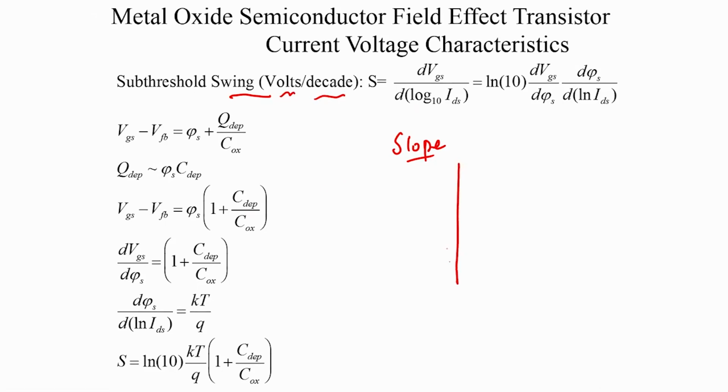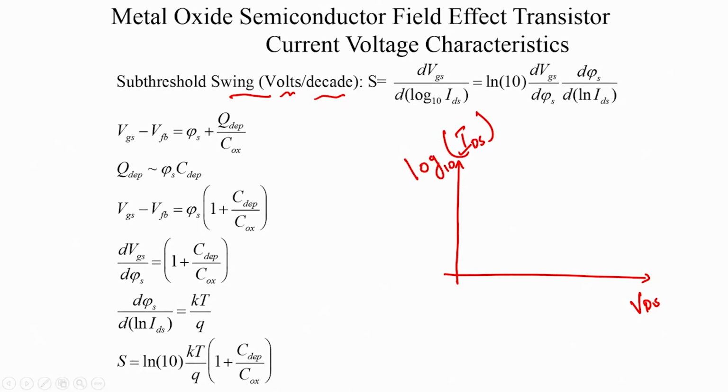It means that if you plot the current-voltage characteristics on a log scale, so we plot log IDS, to the base 10, versus VGS, the gate to source voltage. Till a certain point it is all basically off, and then from say VFB to VT, well, it is not off very far below VFB, just to keep things a little accurate. So, let us say it is off around this region, and from VFB to VT you start having diffusion defining